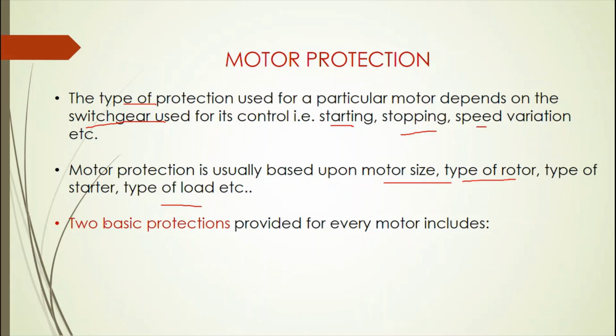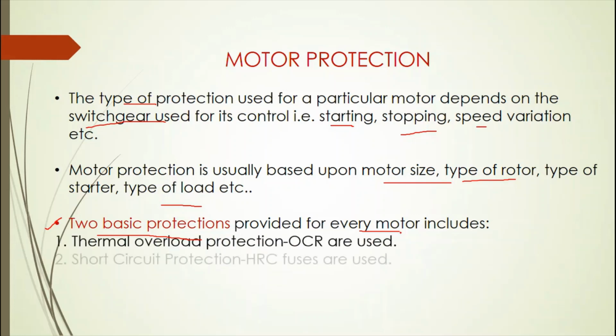Also, this is important, please note it. There are two basic protections which are applied for every motor. These are thermal overload protection and short circuit protection. For thermal overload protection, overcurrent relays are used, and for short circuit protection, HRC fuses are used. These two basic protections are applied for every motor, so you will see these two protection techniques in every motor.